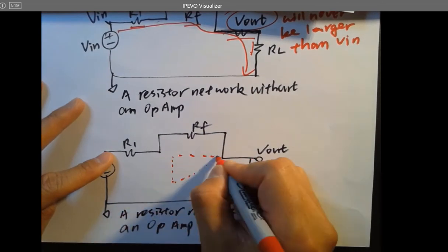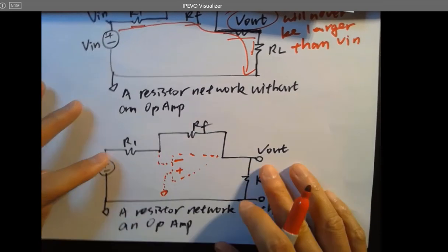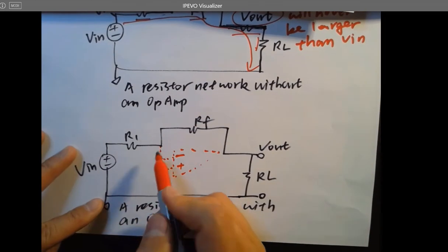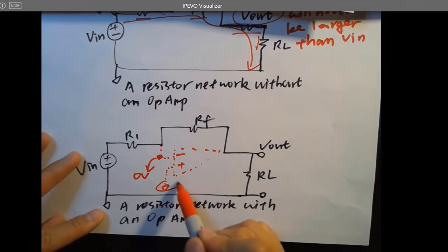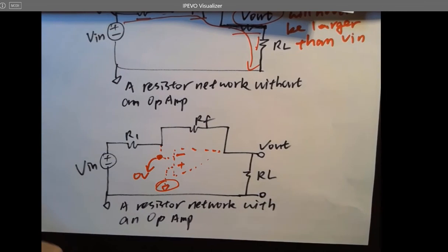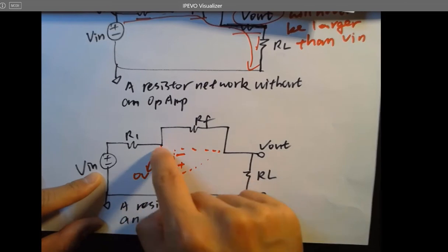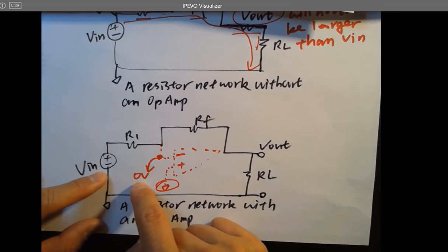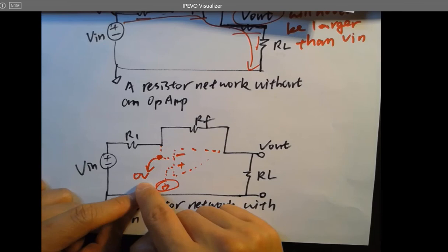so if you have an op-amp like this, all right, that's an inverting topology. This pin will be dragged to where? To 0 volts. It's a virtual ground because of this guy. So what's going to happen is you have a V in here, but I'm sorry, this point is going to force the voltage to be dropped towards the lowest potential possibly in the circuit, which is 0 volts. So it's going to force the voltage to be dropped drastically over here to 0 volts.